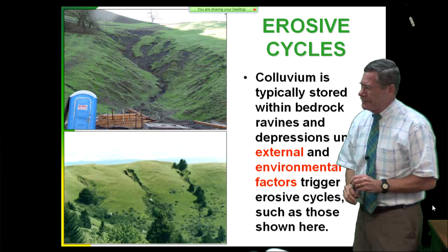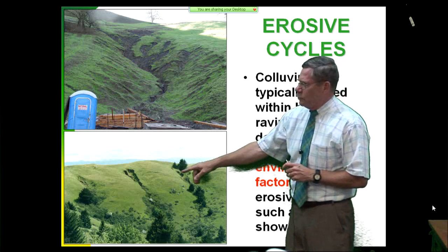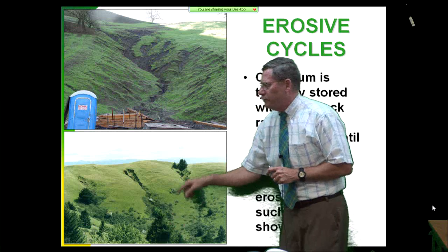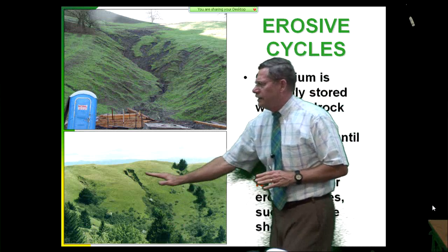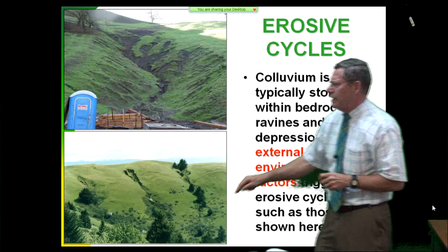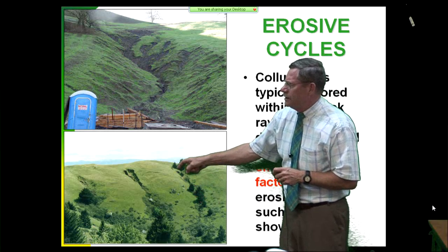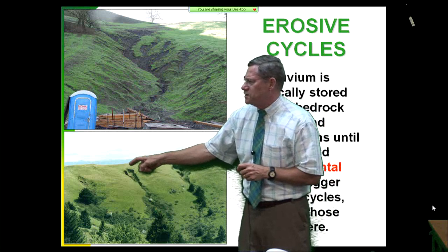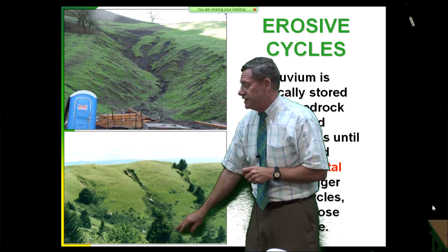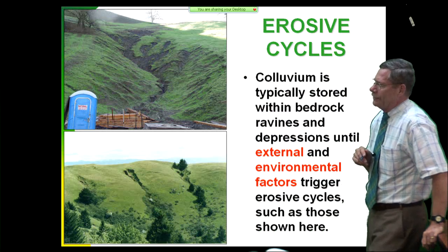If we go up and look at these erosive cycles, they're very, very frightening. Here's some up above Muir Woods National Monument in Marin County. These basins, these colluvial-filled ravines, didn't have any kind of failure until 1967, January 67. They started evacuating at that time down here low, and each decade, every 8 to 15 years, they've had a significant event. Now, a significant event, this one in 1986 spewed 30,000 cubic meters of material. It doesn't look that big. 30,000 cubic meters came out of that one in one event over Thanksgiving weekend.